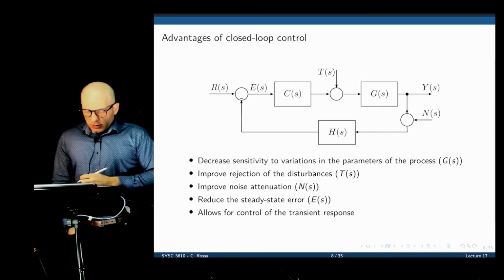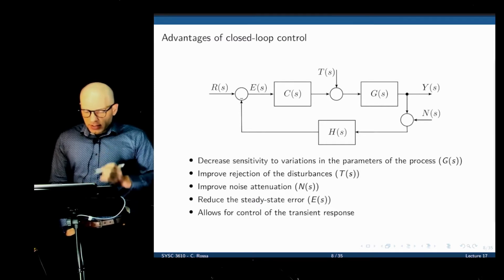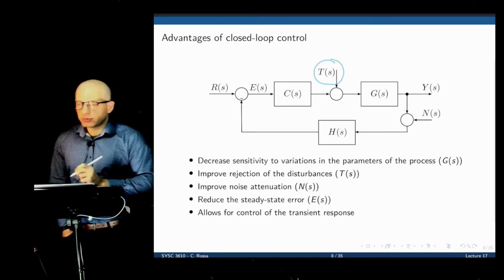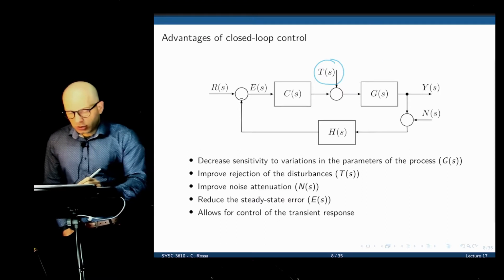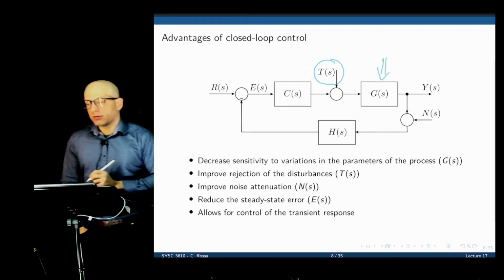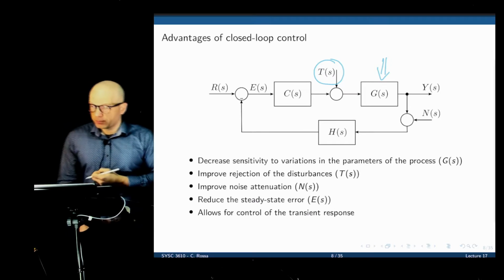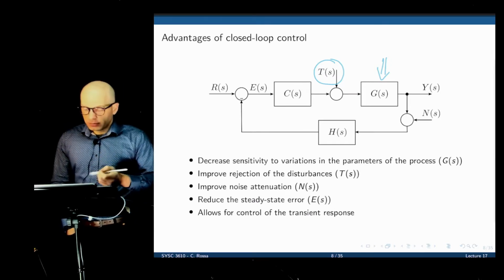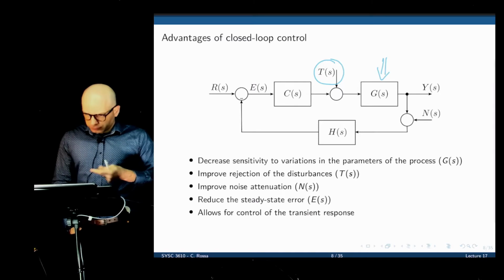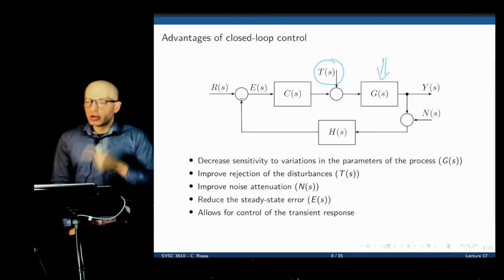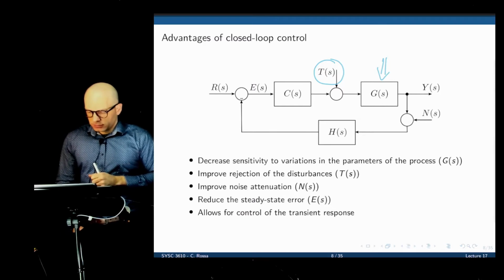So what can we further infer from this control scheme? The main thing is that the control loop that we devise here has 2 main functions. One is to compensate for the effects of disturbance. The other is to compensate for the effect of mismatch in the model. For example, if you got a parameter wrong in our model, it's not as critical as if we had an open loop system, because now the error will compensate for that.